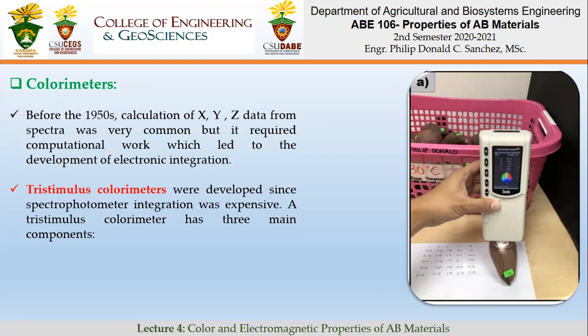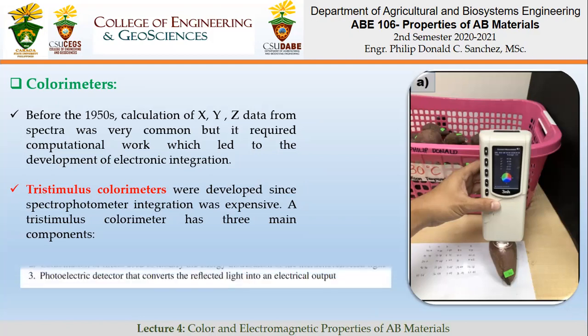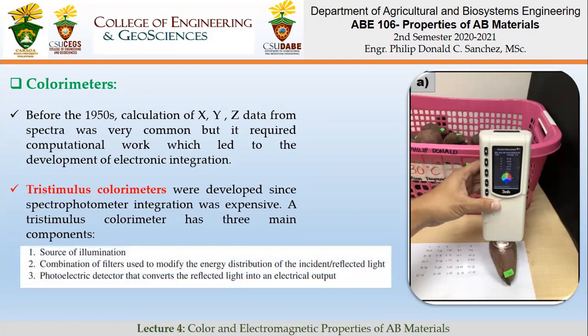Okay, and then, based on the picture, after getting the color value of that part of the sample, you need to get the color values of the other side, and then the other side, and then you get the average. Then you have to calibrate the colorimeter again on a white cloth or white paper to get the reference, to calibrate the measurement characteristics of this color measurement.